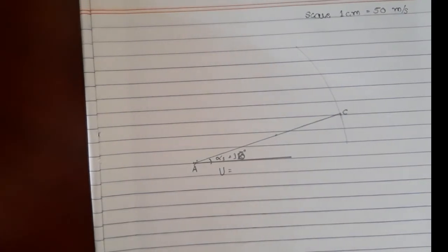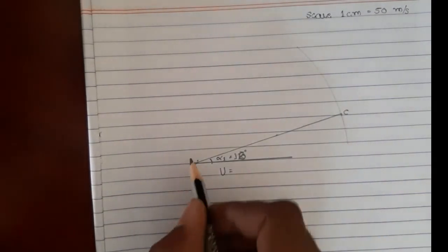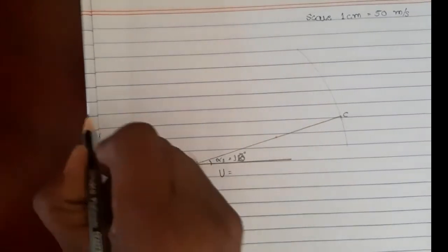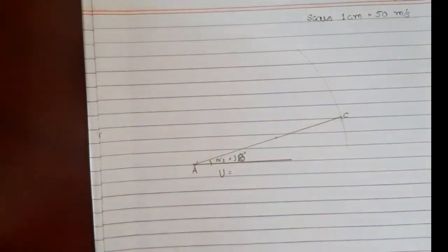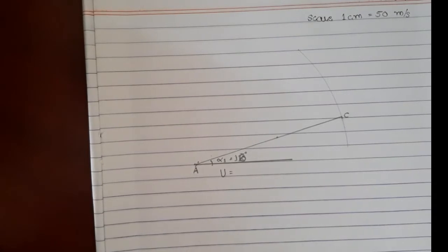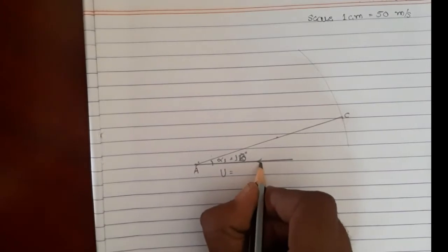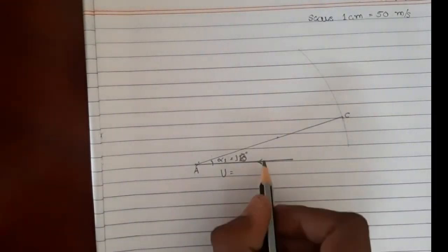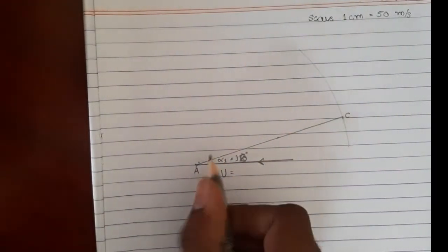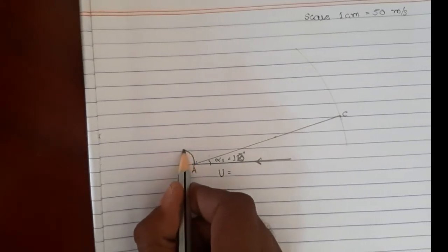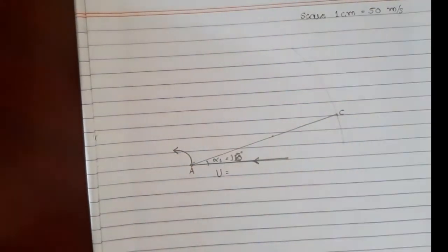That is what we drew just now. Now, V2 is also given; from the same point V2 goes at an angle alpha 2. V2 is given to be 100 meter per second. So 100 meter per second means it becomes a 2 centimeter line at an angle 110 degrees with the direction of the blade motion. So if this is the direction of blade motion, alpha 2 is 110 degree with respect to this line.